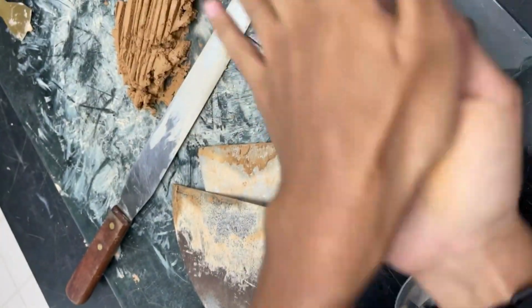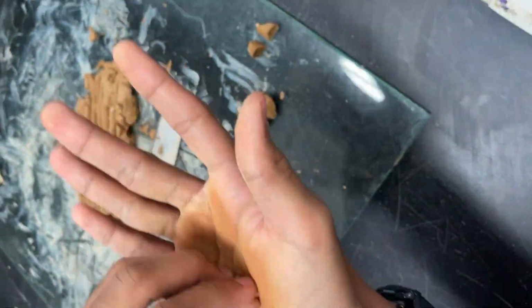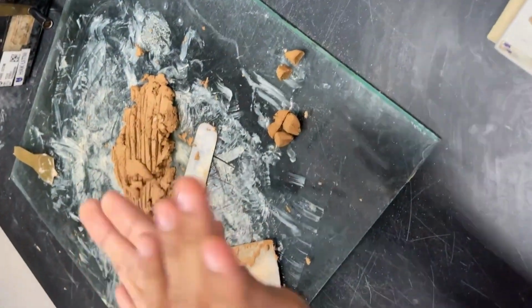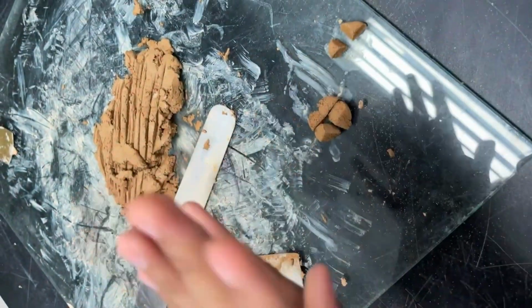The soil was then formed into an ellipsoidal mass by rolling it between the palm. Sufficient pressure was used to roll the soil into a thread of uniform diameter. The soil is rolled until some cracks appear on the soil. When the diameter of the thread reaches the correct diameter, which is 3.2 mm, the thread is broken into several